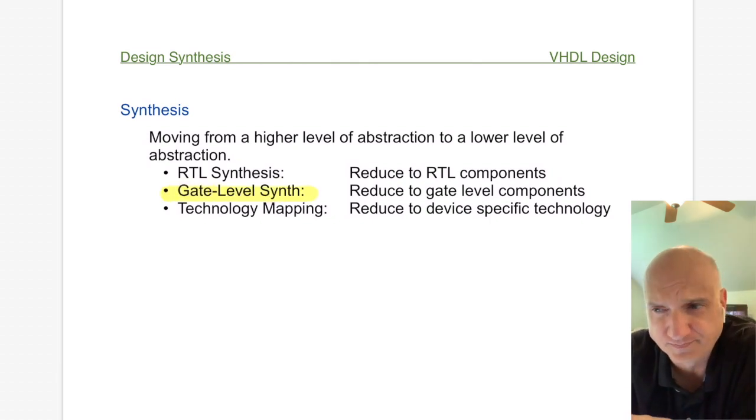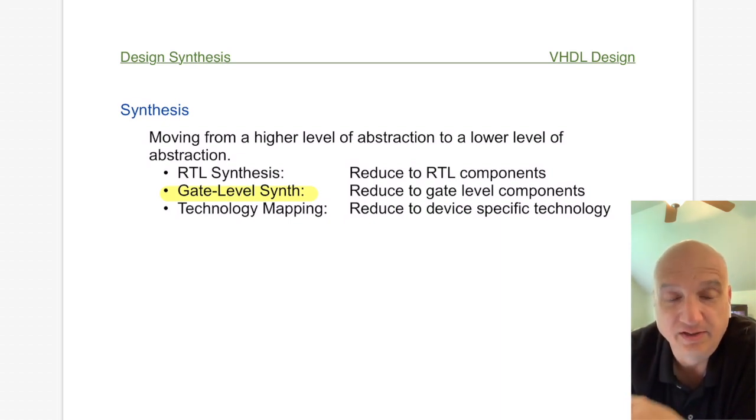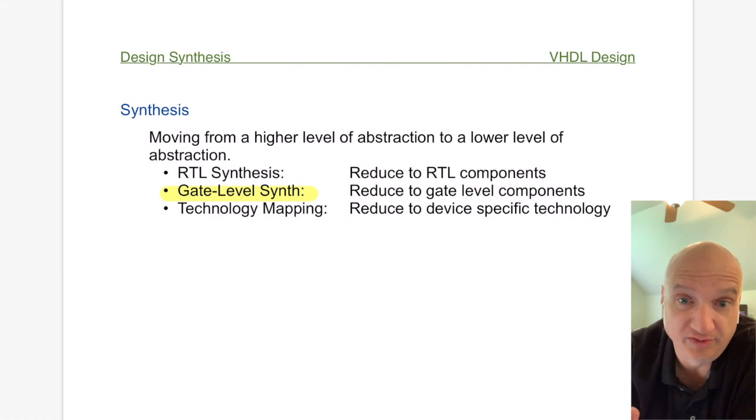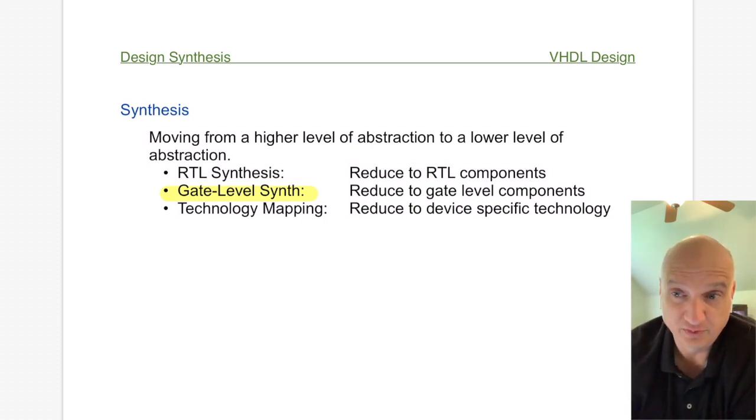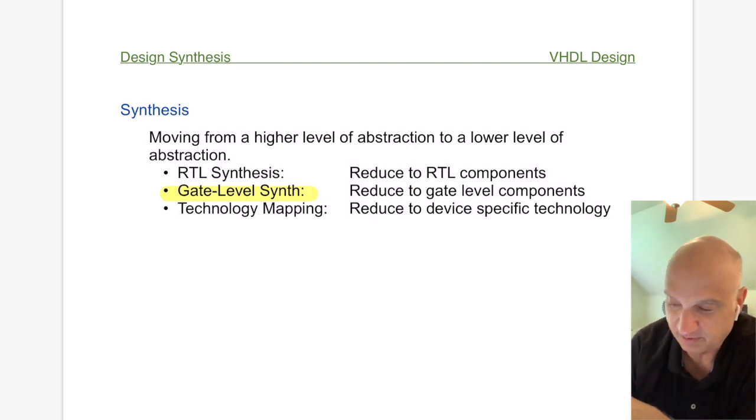Now, in digital, you can describe anything combinational logic wise as gates, any logic gates, AND, OR, that kind of stuff. Add in a flip-flop or two and you have elemental storage, and therefore you have a complete digital system. It could be described as a series of gates and flip-flops, and that's it. So every digital system can be described that way. It gets complex when you get more complex systems, but it works. That's how everything can be defined.